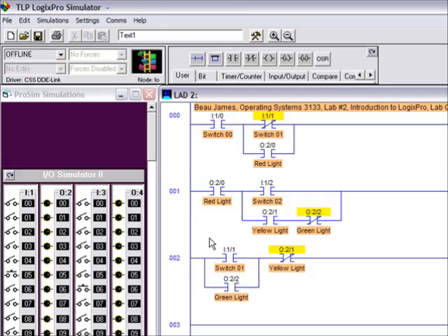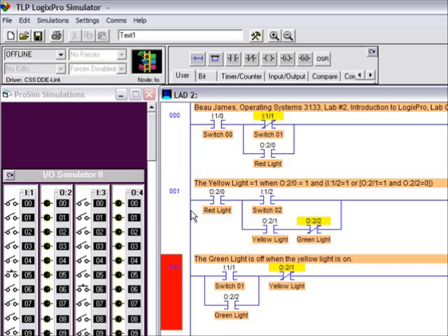Okay, so we can go ahead and add the comments that are listed on page 9 to rungs 1 and 2, and we'll go ahead and complete that now. So you'll notice now that we've added the comments to rungs 1 and 2, the rung comment serves as an indicator to the operator, in this case the programmer, what exactly is happening on each rung, to give it further description, to give it some meaning, so when you troubleshoot or come back to these rungs, you can quickly identify what each rung is doing and continue on to the next step.